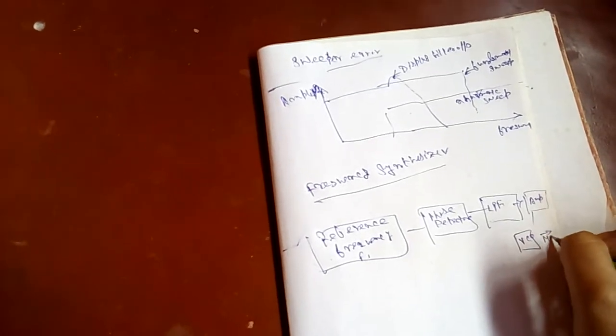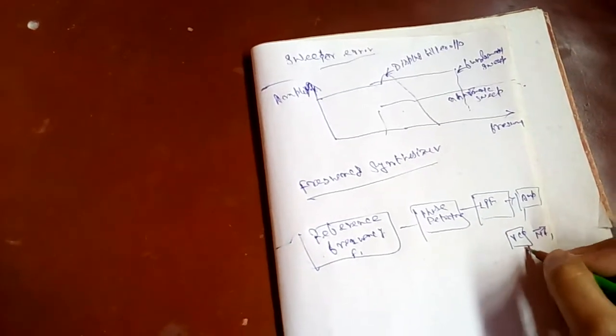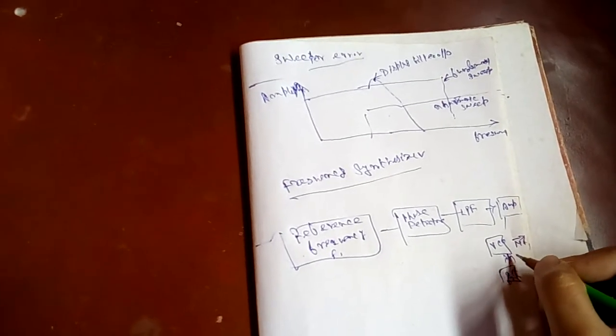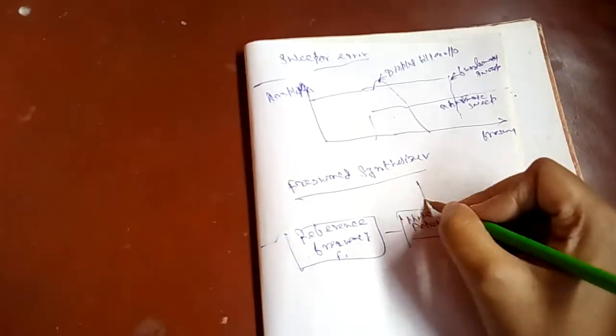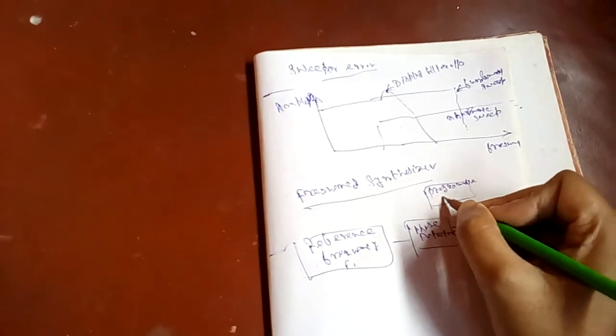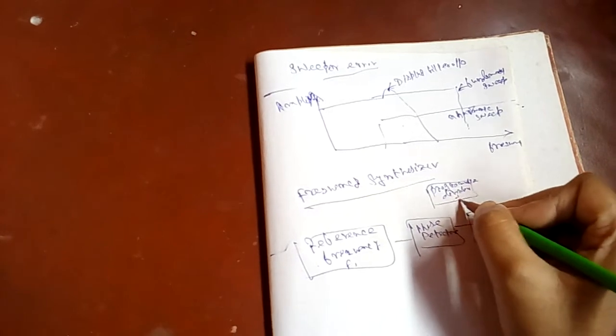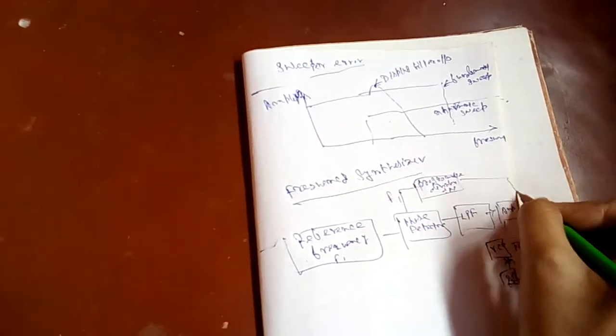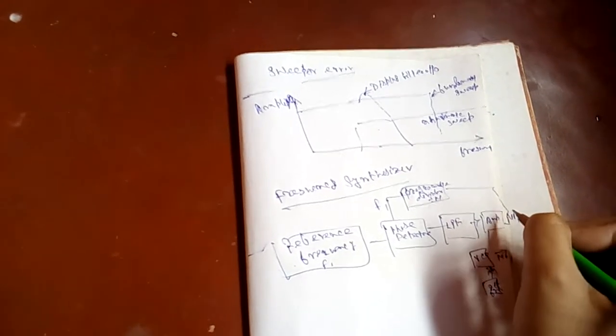We take N F1 from the VCO, we can set the frequency, and the frequency programmable N divider divides by N, so at the phase detector we compare with F1.